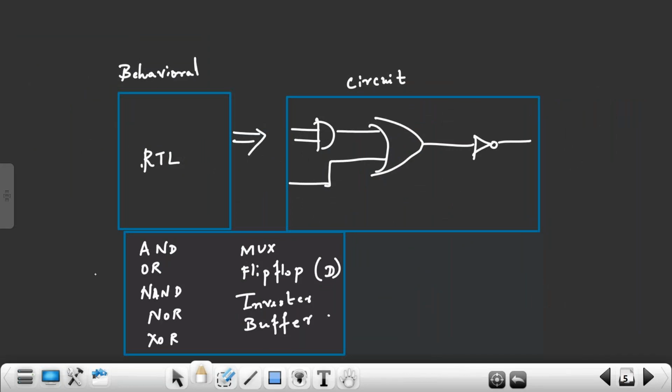So for all the standard cells, timing and power information is present in the .lib file. Timing means delay of the cells, and power means how much power each cell is going to consume while working. You have different types of power again: leakage power, switching power, short circuit power. All those things we will discuss in PD basics and even in physical design. So delay information and power information of all these cells is present in a .lib file, which is called a Liberty file.